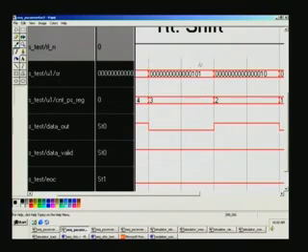So you can still see that some of the patterns are still here, 1, 0, 1 here, and once you right shift this one gets dropped, so 1, 0 here, and you can see that data out is going alternately low and high, and all through data valid is high, and end of conversion is 0 because all the bits are not serialized.